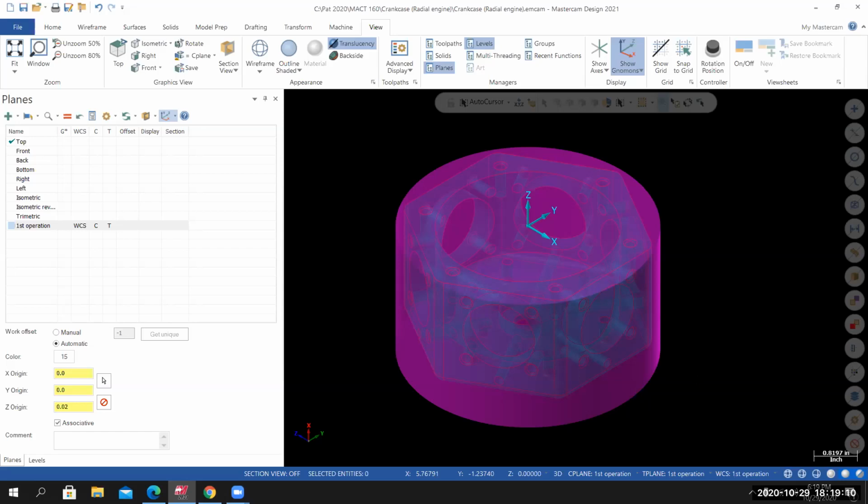How would you hold on to this part on the machine? Could you hold on to it in a vise? Maybe a fixture, I don't know. Yeah, so what we do with this part is we take a soft jaw. Now we've made soft jaws, right? Remember the mill soft jaw project? Those are designed, or the intended use of those is to cut a profile into the aluminum jaw so we can hold on to oddly shaped profiles or something that won't be easily held with your typical hard jaws. Does that make sense? Yeah.